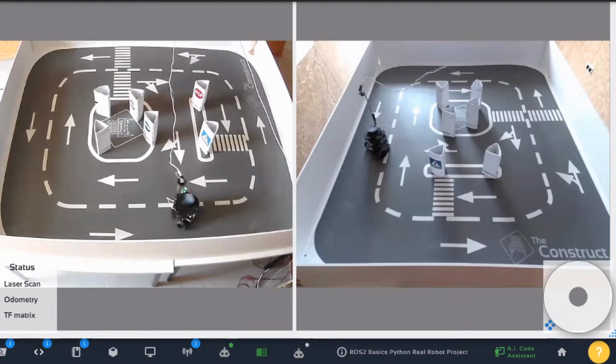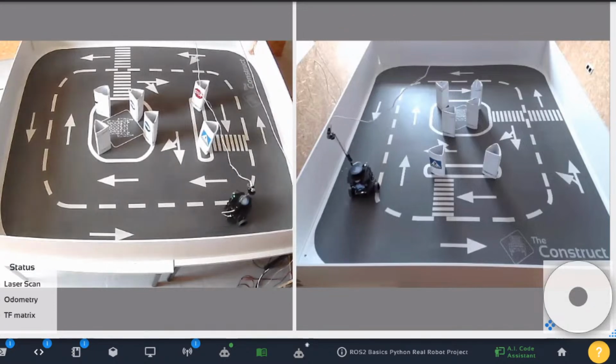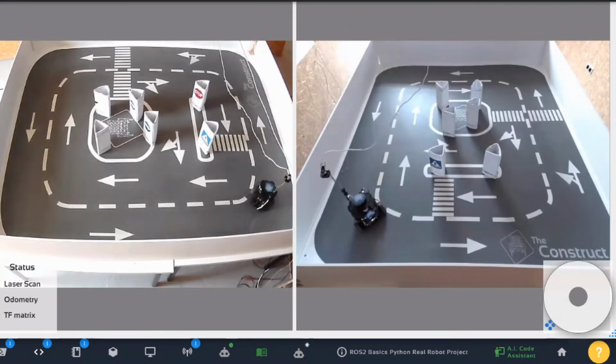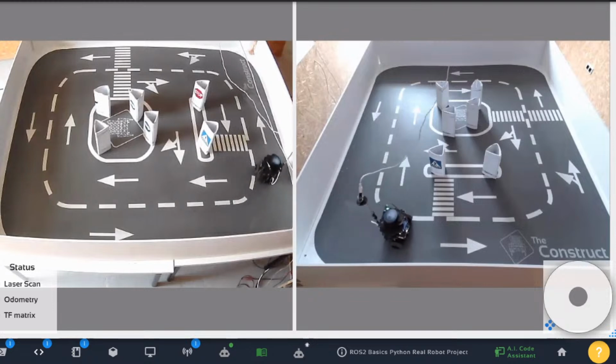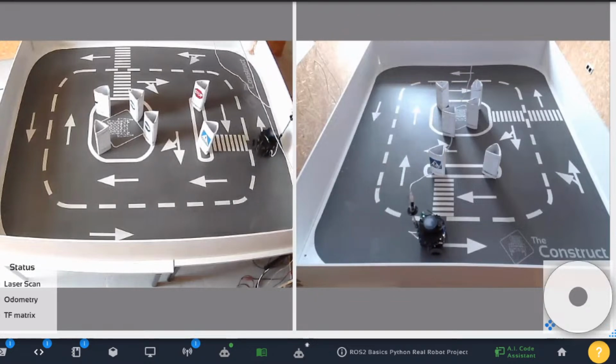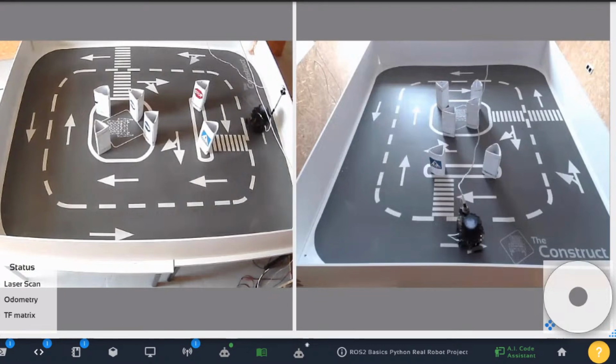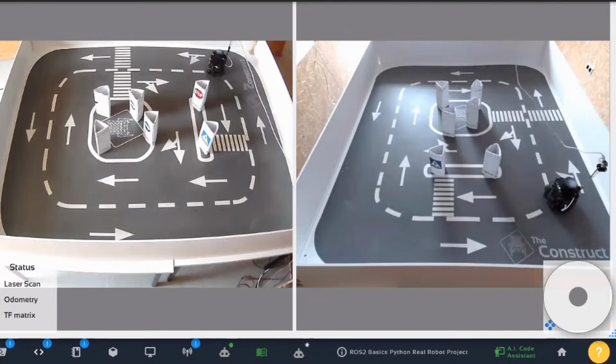So the robot located the wall, decided that it's in the correct position, aligns itself to the right, and then follows the wall. When it arrives close to a frontal wall, it will increase the rotational speed. It will enter a banking mode to avoid the wall. The walls are not symmetrically located, so from time to time, each of the turns against the wall dislocates it from the center part of the track.